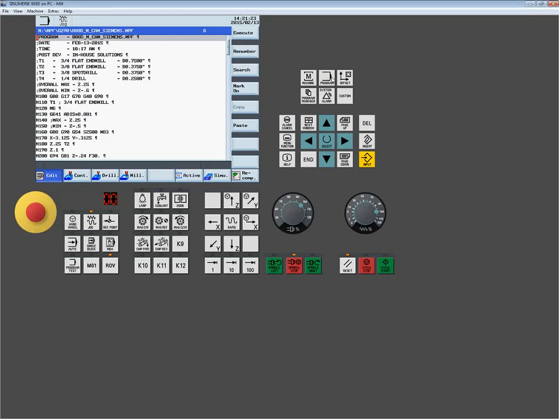If we look at this program, we're going to start to see a few things right here in the beginning. We are going to see that this is going to do a tool change to tool 1. So it physically loads the tool here with the M6 statement. They have a corner rounding function initiated. Then we have some rapid, some basic header statements, what work coordinates using, spindle speed command.